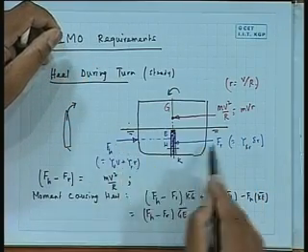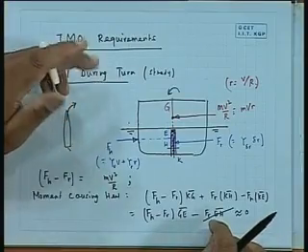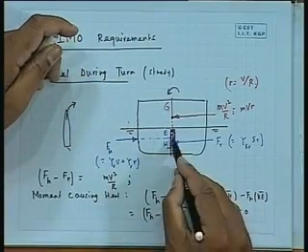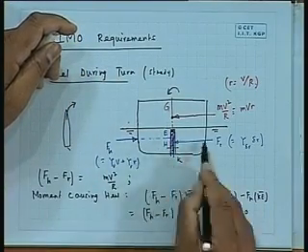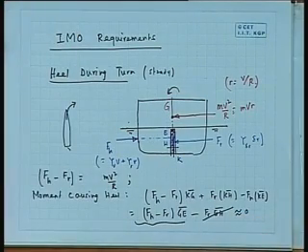So, therefore, Fh and Fr are more or less collinear. One can always try to find out where the center of action is, but it turns out for all ships this is very similar, so that EH is almost 0. This is why it is written this way, EH, because they will act more or less in the same line. So that my moment turns out to be like this. This is the reason for writing that. Okay.